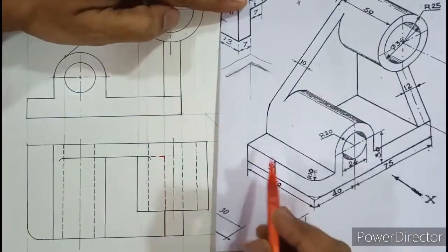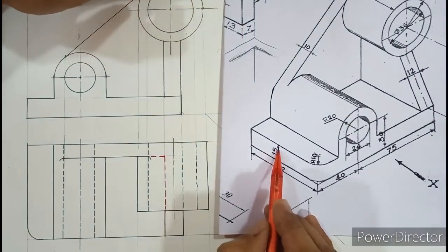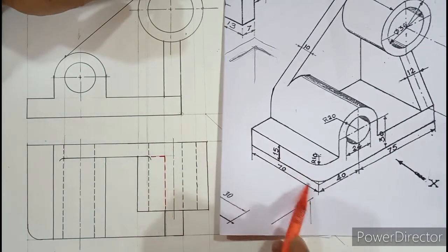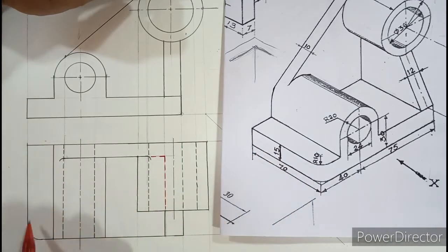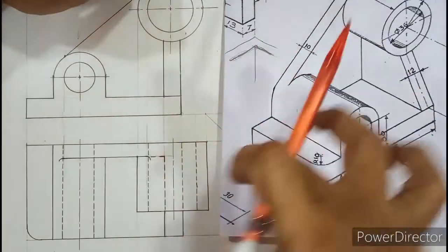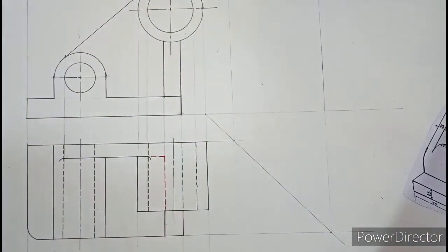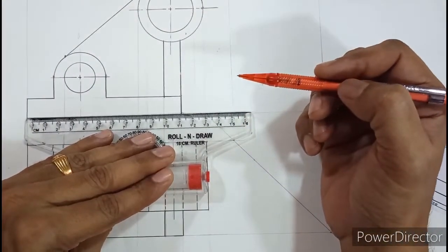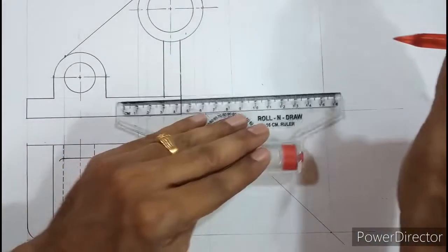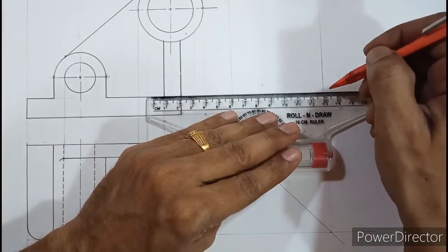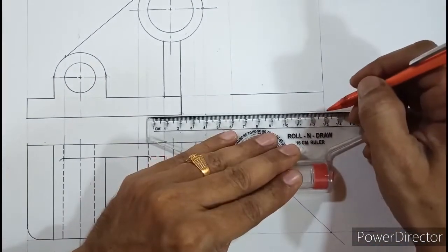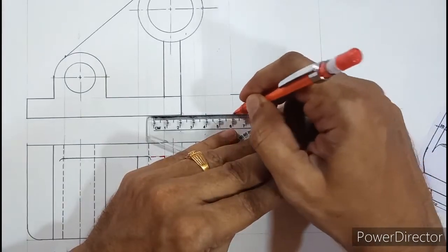So this surface which is 15 mm high is same as this height 15, and the width is 70, isn't it? So that width is same as this width. So we need to project 15 from here and 70 from the top view. So let us do that quickly. So this dimension is, this height is 15. So from here I'll extend this little above, and we will draw this dark double trace, left to right, right to left.